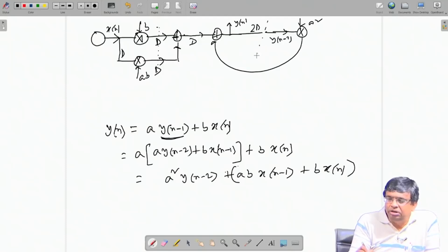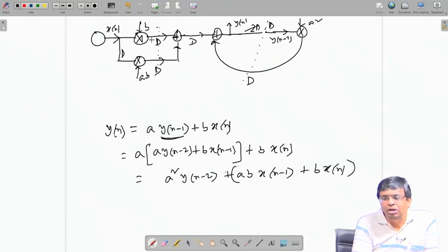So, if I now do cut set retiming, I just reduce 2 d to 1 d, that is take out one delay from this side, bring another delay on this side. Okay. So, now you see both this path is delayed, this path is delayed. So, adder and multiplier here or multiplier and adder, they are not coming in the same cycle. So, these are not delay free paths, which means on that node which takes maximum time, there is a multiplier that I have to take for the critical path. So, it is just T m, earlier it was T m plus T a. So, this is how I can bring down the critical path.